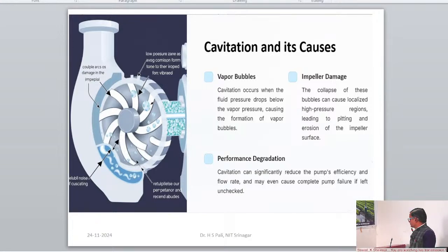The reason for feet or meters is that pump manufacturers only know how high their pump can push a liquid. They do not know which liquid your system will be pumping. As each liquid has different properties, the pressure will vary depending on the liquid used. However, the height it can be moved by the pump will remain the same. For example, we have this pump which can provide 125 feet of head. If we use it to pump water, the pressure will be around 54.25 psi. But if we were to use it to pump milk, then the pressure will be around 56.15 psi. That's purely because of the properties of the two fluids. So the pump is working on two things.